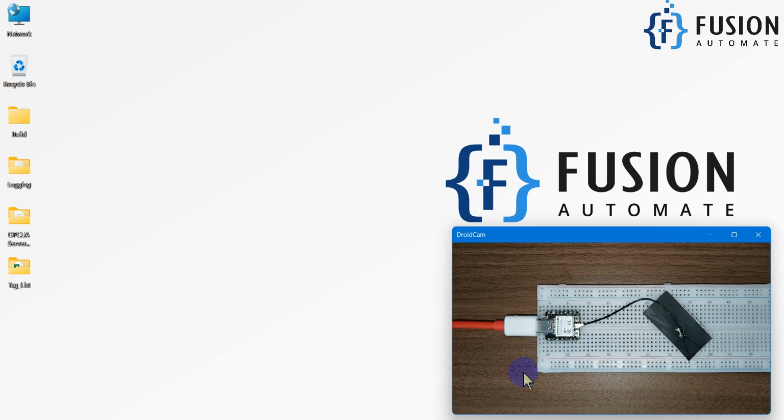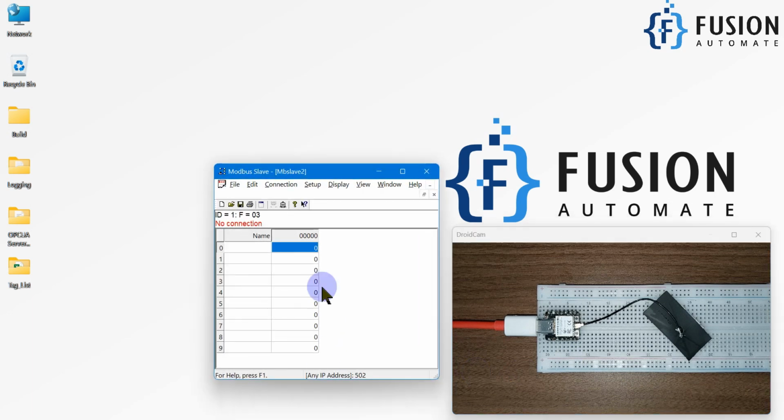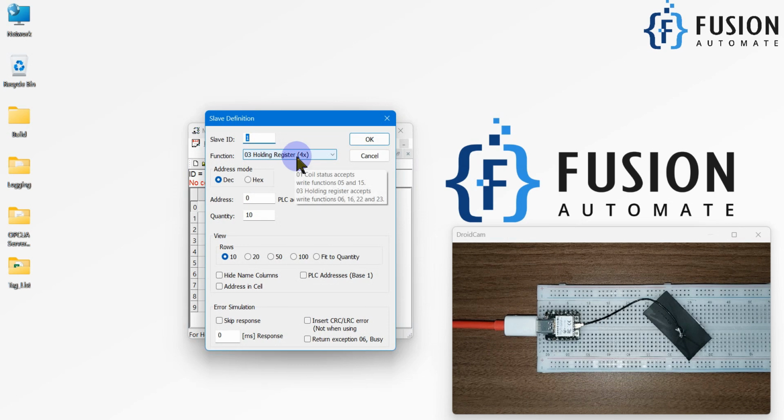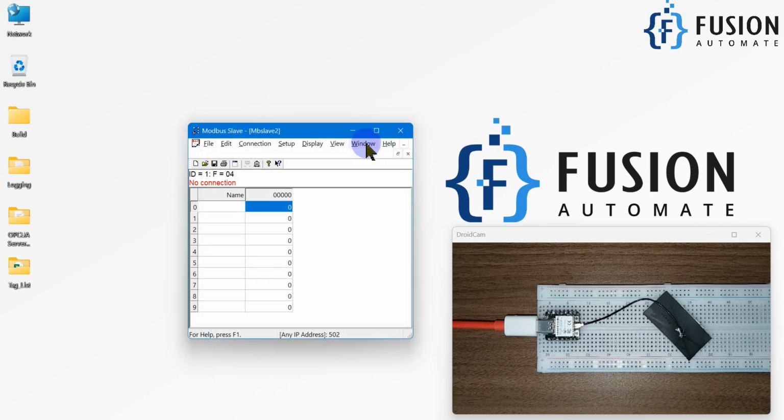First of all, we have to create our own Modbus TCP/IP device in our system. I'm going to use the Modbus Slave software to create it. I click on Setup, go to Slave Definition, and I want to create a Modbus TCP/IP device with the input register, so I select this one. The number of registers I want is 10, the starting address is 0, and I click OK.